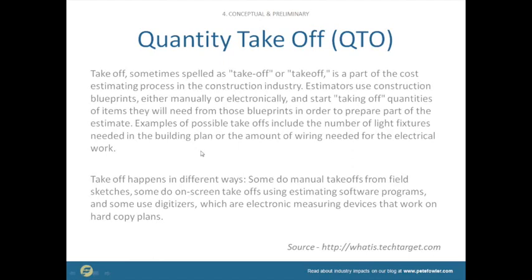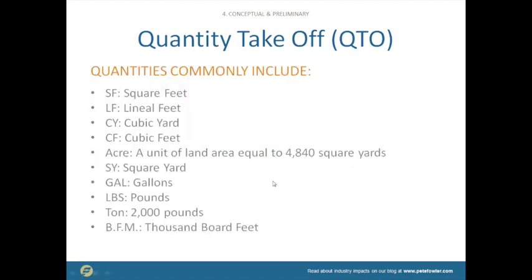It depends. If you're doing 1 square foot or 100,000 square feet, the cost per square foot is profoundly different. They have no connection to one another. So be careful with square foot prices. It's powerful. You can do a quick estimate that way, but it can also be very dangerous. So, commonly used quantities: I'm not going to go through each of these: square feet, lineal feet, cubic yards, etc.